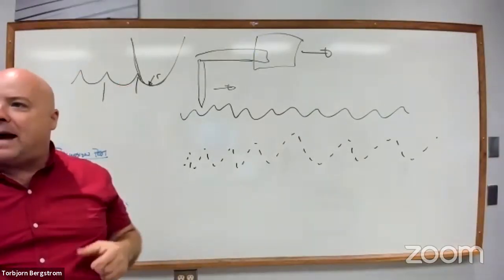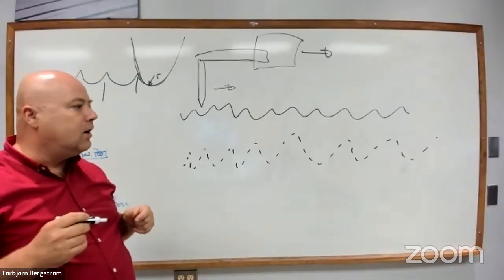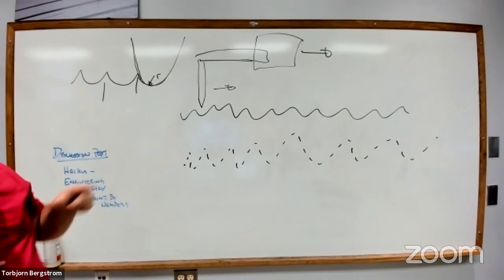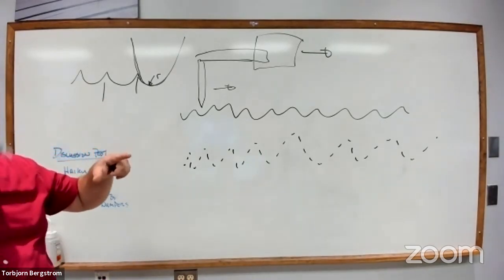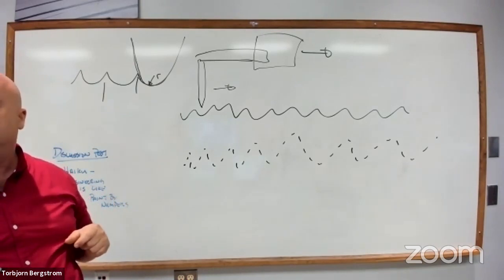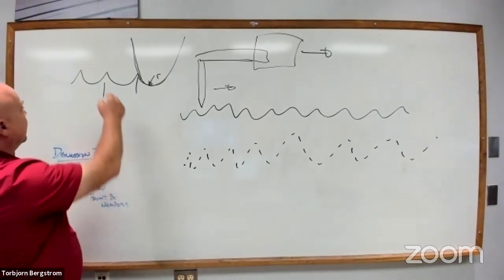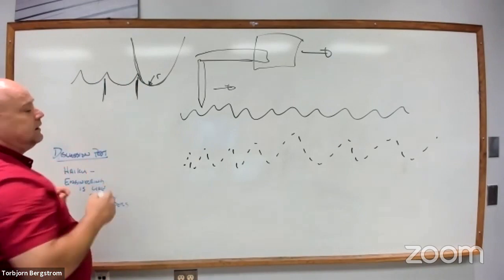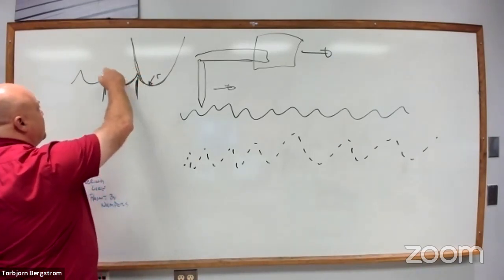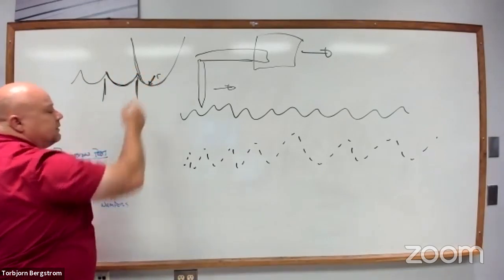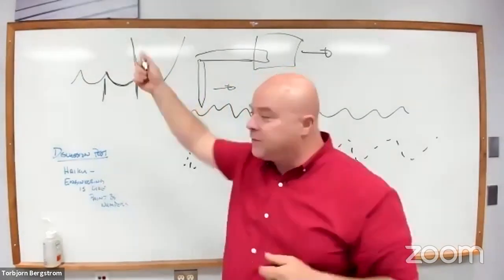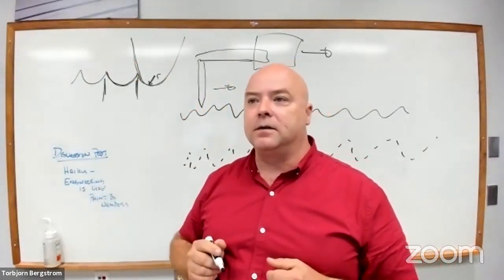revolution, right? So you can imagine if you zoom in tight on a turned surface, you'll end up seeing a little spiral groove from the tip of that tool as it goes across the surface. And this distance is the feed length per revolution. And the radius at the bottom there is the radius of the tool. So this kind of profilometer is great for measuring the surface roughness of a turned surface.